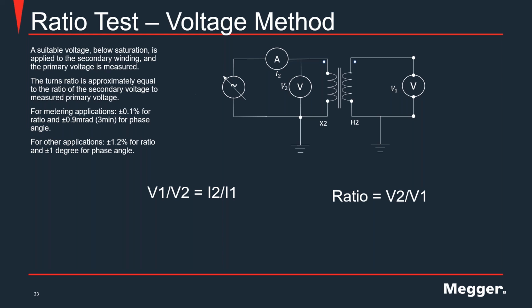Now coming to the question that Michael asked: how do you test CTs that may have a very high knee point? Some CTs may saturate at 4,000 volts or even 10,000 volts. So to answer that question, just think about what is happening when you're doing a saturation test. You are building up enough flux to saturate the CT. And the formula for flux is voltage times time. So as I increase the voltage, you are increasing the flux and you are saturating the CT.